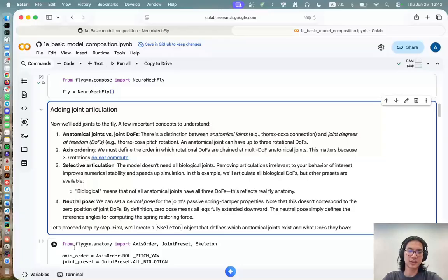But also joint degrees of freedom. For example, is the joint between tibia and tarsus a ball joint where you can rotate about all 3 axes? We know this is not true. In fact, it's a 1 degree of freedom joint where it acts more like a hinge instead of a ball joint. So this kind of information needs to be defined.